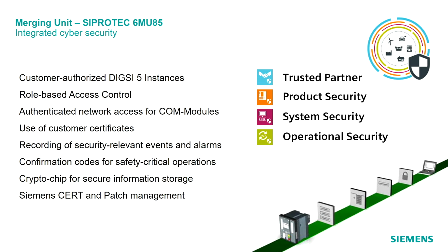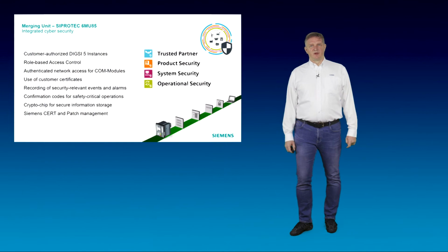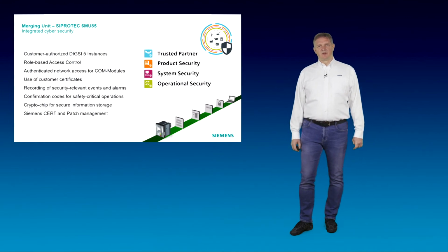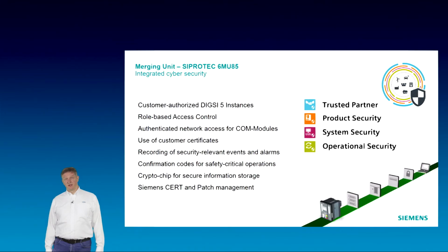For such a system, reliability and security is a must. Besides the rugged designed hardware and by standard conformal coated electronic boards, special care needs to be given to cybersecurity. Cybersecurity is embedded in ZBTech 5 and provides secure communication with TLS, IPsec and client-server authentication, firmware integrity checks, product CERT for vulnerability handling, centralized account management and role-based access control, centralized security event logging, future readiness with PKI support.